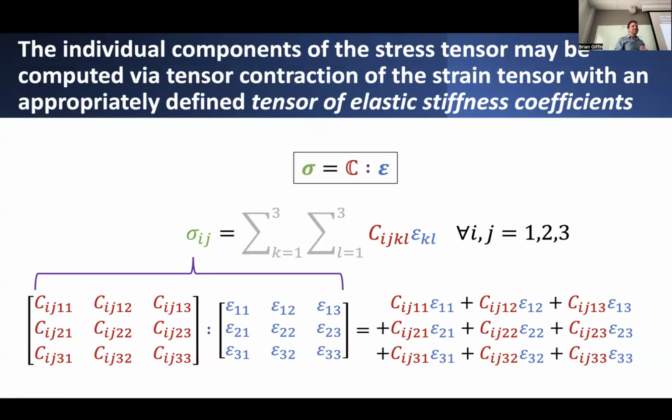For that particular component of stress, we can determine what that component of stress is, expressed in terms of this tensor contraction between all the components of strain and some subtensor comprising this collection of elastic stiffness coefficients that would show up equivalently in that big matrix we'd established, that 6 by 6 array of stiffness values.